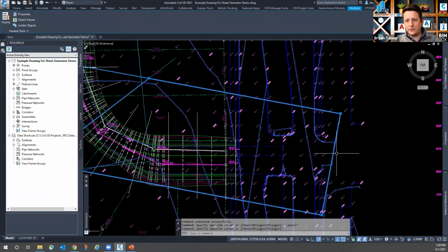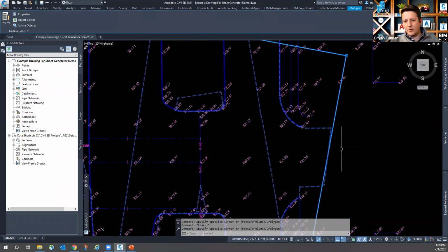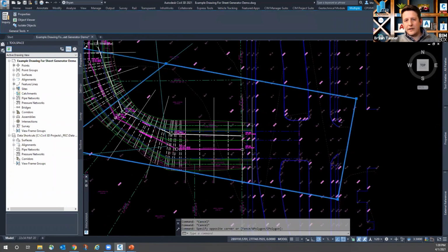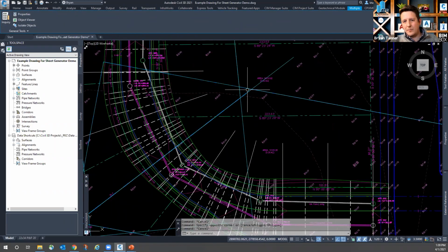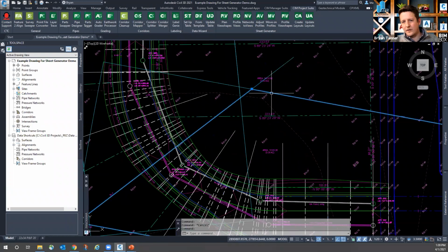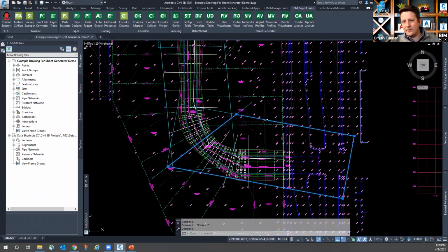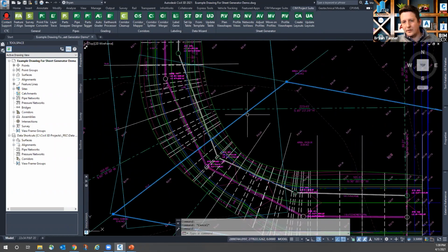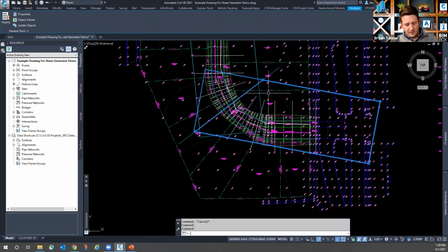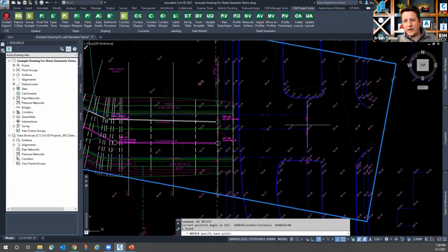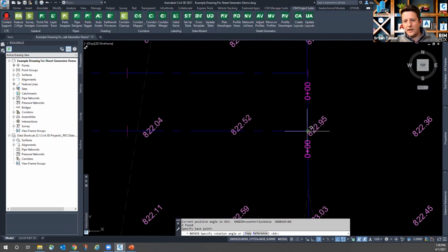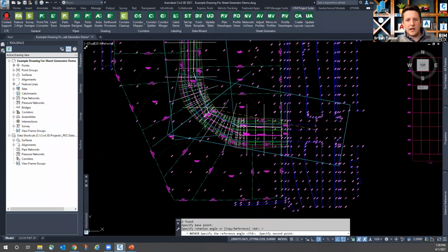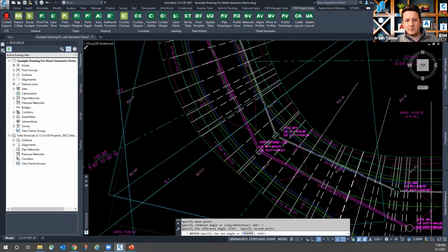I don't want to select my viewport or my X reference there, but I can select my view shape, and here's my drafting shape, my drafting guides. Anything beyond that polyline will not show up in this first sheet, but there's my overall view shape. So I can select both of those, and use a regular old AutoCAD rotate command and rotate it about my starting station and use a rotate associate.